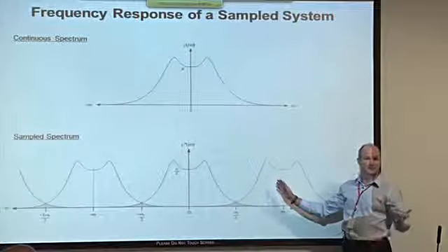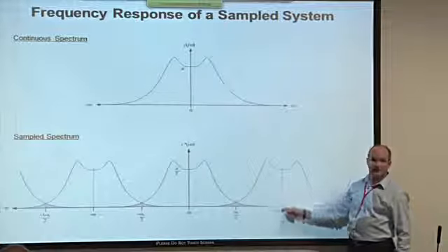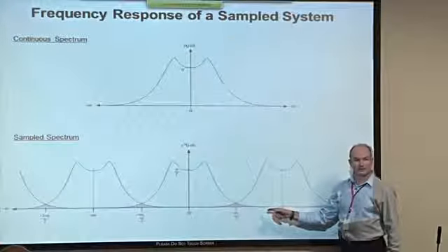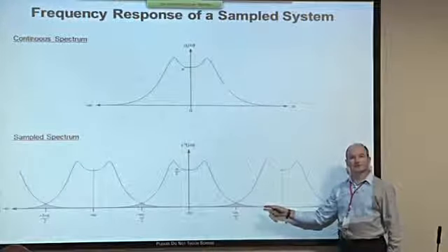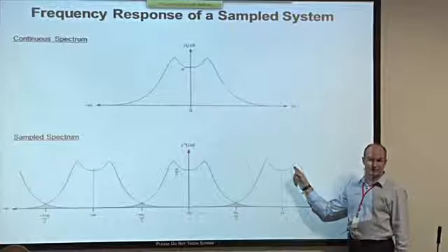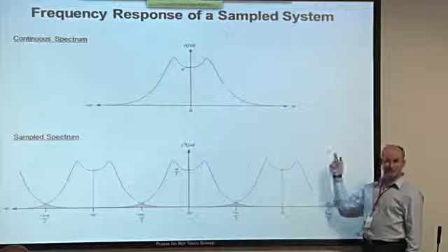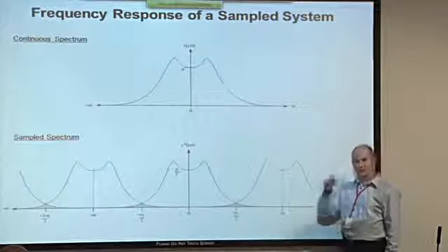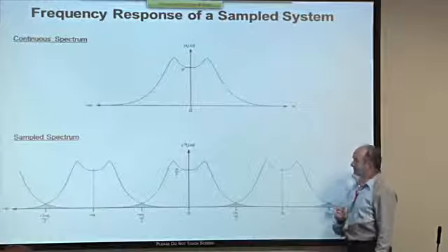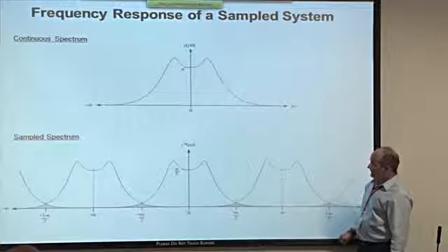In terms of the sine wave example that I showed you a couple of slides ago, we had a sample frequency of 40 hertz, and yet 5 hertz and 35 hertz looked exactly the same. So can you see now the next one would have been 45 hertz. And then 75 hertz, 85 hertz, 125, 150, and so on. Those are all frequencies that would have given you exactly the same set of data points because of aliasing. Now, in order to avoid aliasing, there's only one way.